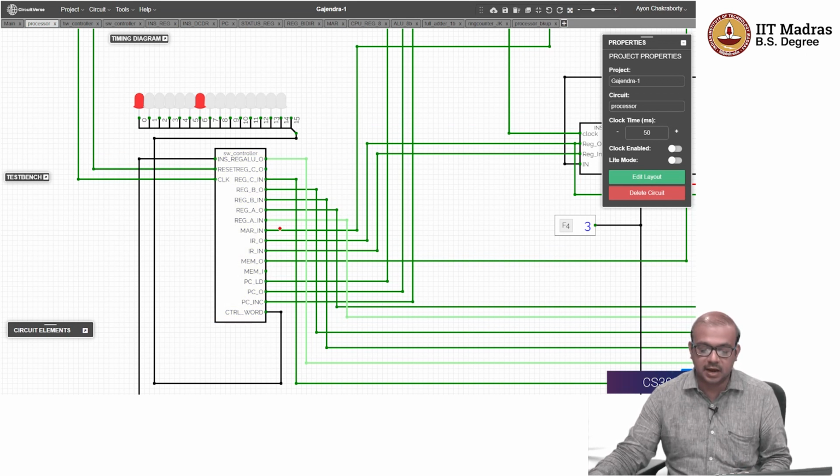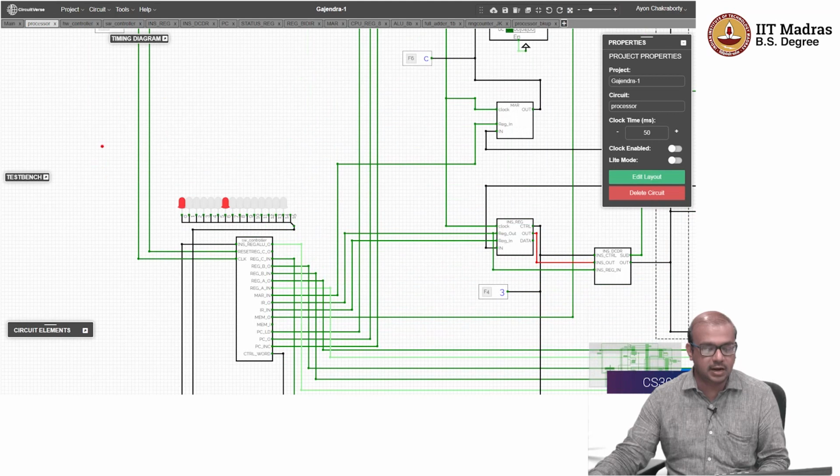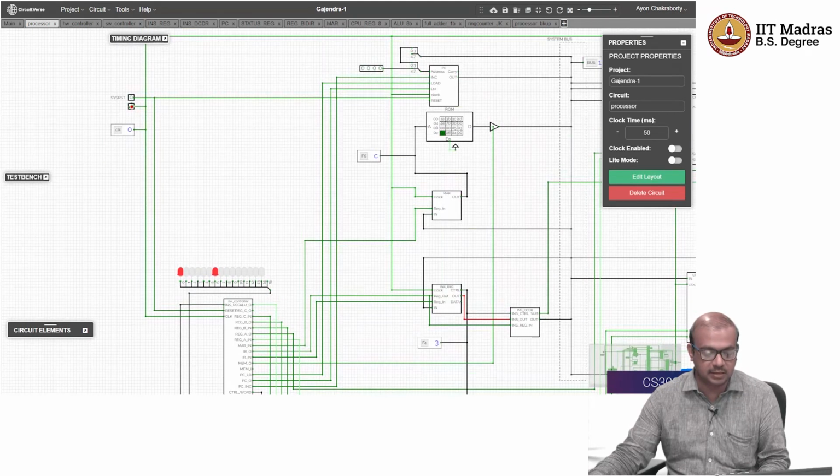So it is very clear that in this particular part, an add instruction or a subtraction instruction is going on, and the ALU is outputting to the common bus, right? That is why it is high, and register A is getting loaded by that value. That means that the computation has been finished. The ALU is trying to put the value into the accumulator, or register A.